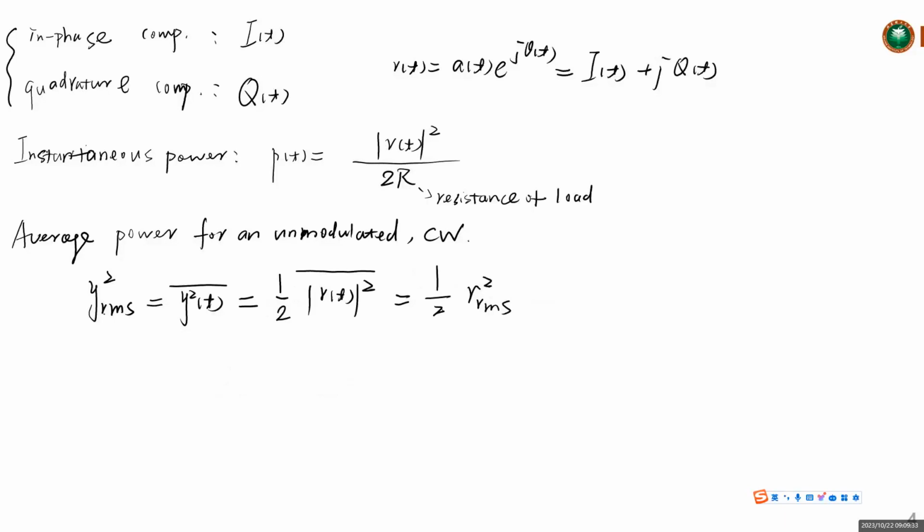This is an important expression. So that means sometimes if you want to take measurements on the modulated signal or the unmodulated signal, you need to take care of the maximum power input to your power meter, to avoid it being destroyed actually.